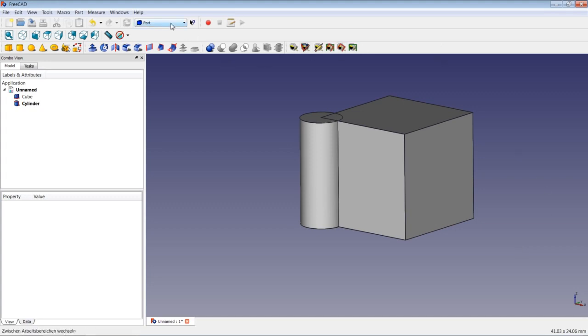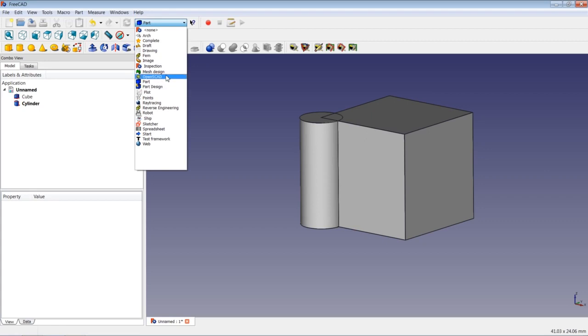As you can see in FreeCAD, we have a Mesh workbench for dealing with meshes, and when you are working with solids, you will use most times the Part workbench, which is also called the Part module workbench, and the Part Design workbench. In some cases, you will also need the Draft workbench for special operations.